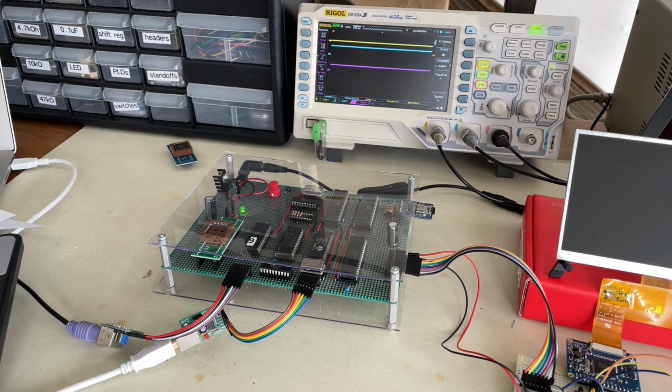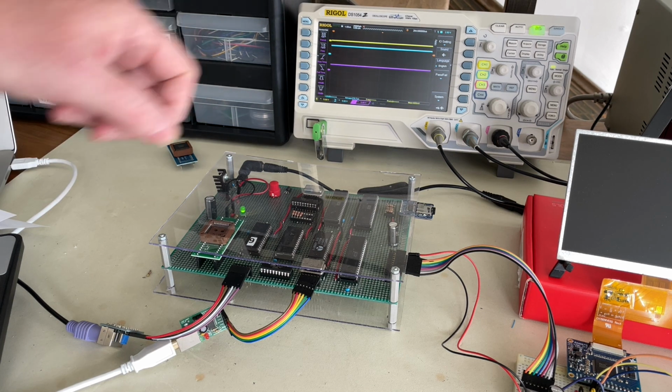When we look at the software, I'll talk a little about how I map signals onto different parts of the interface. Although SPI can be a shared bus, I have them running through different ports, although once the 65 SPI is up and running, that might not be the case. And I have the reset signal mixed in there as well. So in addition to the 4 regular channels of SPI, I'm also driving the reset signal for these devices.